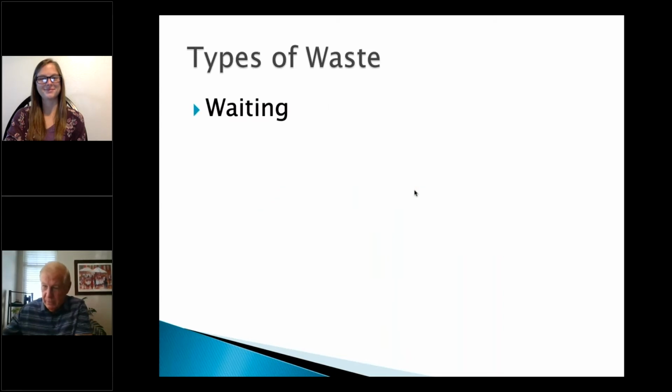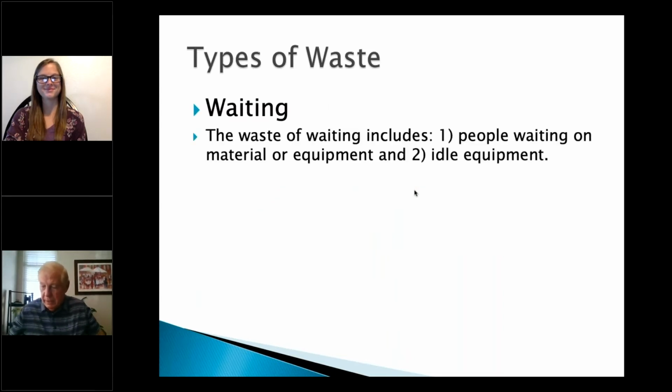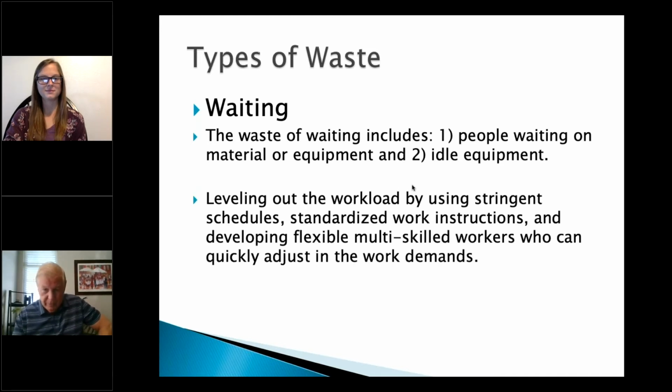So that's motion. Waiting. Waiting is very straightforward, but in a manufacturing operation, it's very key. It's people waiting on materials or equipment, and it's idle equipment. And the way you get around that is from a standpoint of stringent schedules, standardized work instructions, and developing and training multi-skilled workers.